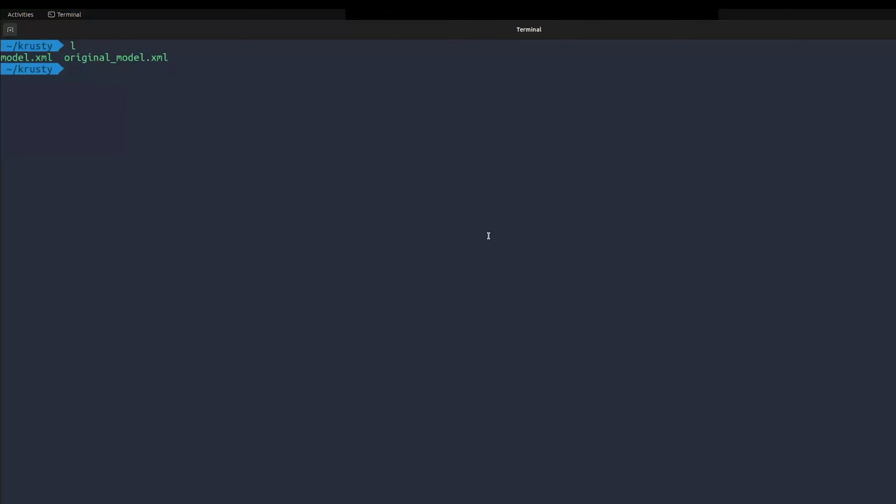Okay, so to set the stage, just like April mentioned, we're kind of in a world where we have an OpenMC neutronics model, and now we want to extend our analysis to some multiphysics application. And what we're trying to support here is a situation where we don't want to have to duplicate effort and redefine the geometry or material assignments of this model in CAD separately in Cubit. So like going back through our CSG representation and figuring out what parts we need to make. Instead, we've attempted to automate that process. And that's what we'll be starting with today.